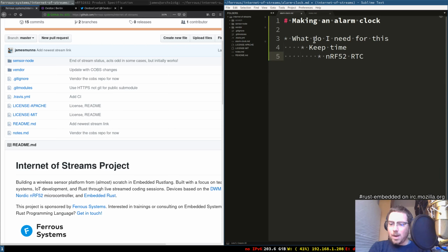And that works pretty well, especially over a short amount of time. If you're just measuring it once, then that's going to be pretty accurate, because the clocks on these processors are pretty accurate. But the problem is they can vary wildly, usually based on temperature, and they're also not calibrated. So you're going to be aiming for 10 milliseconds, and you'll probably get something like 9.995 milliseconds or 10.005 milliseconds, and that works really well. As a human, you won't even notice that.